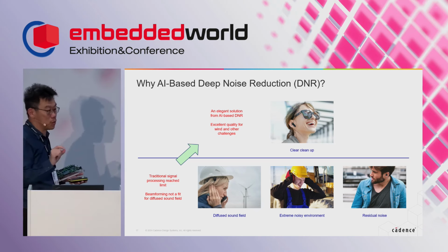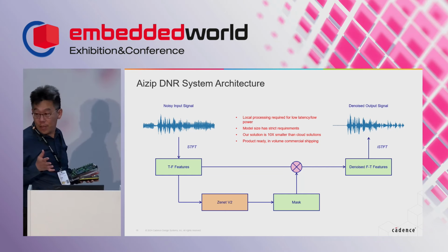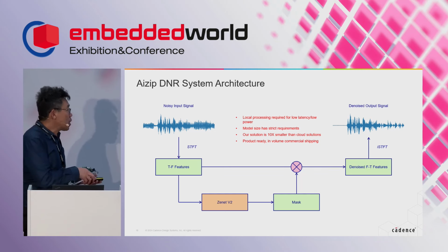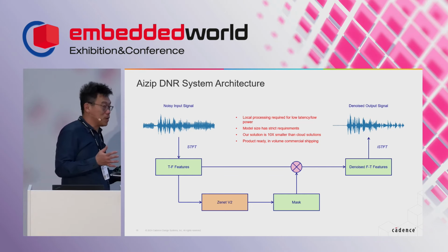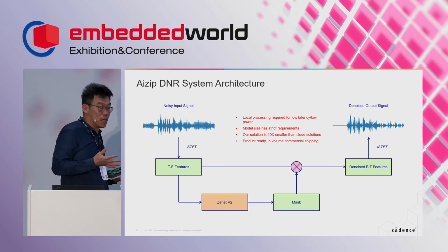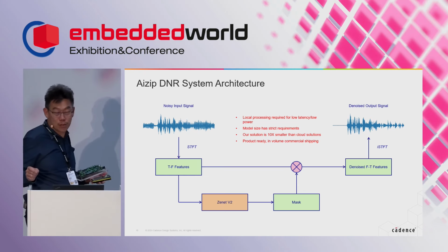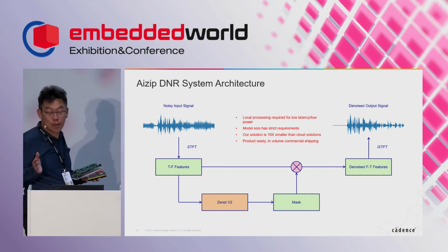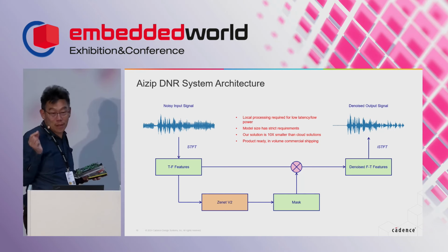So this is a typical block diagram of AI-based noise reduction. The strength of each of the companies marketing different AI-based noise reduction basically is in how they create the model and how they train. But the basic concept is almost the same for everybody, right? So you are competing not on the signal flow, but on how strong your model is, how small it can be made, and how little resource it takes to get the best effect. Because we are not running from the cloud. We are running in a headset that has very little memory and consumes very little battery power. Right?